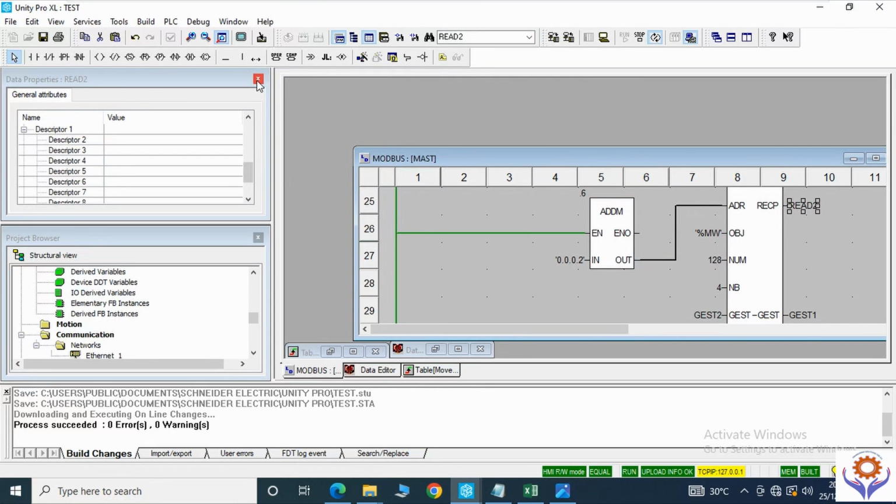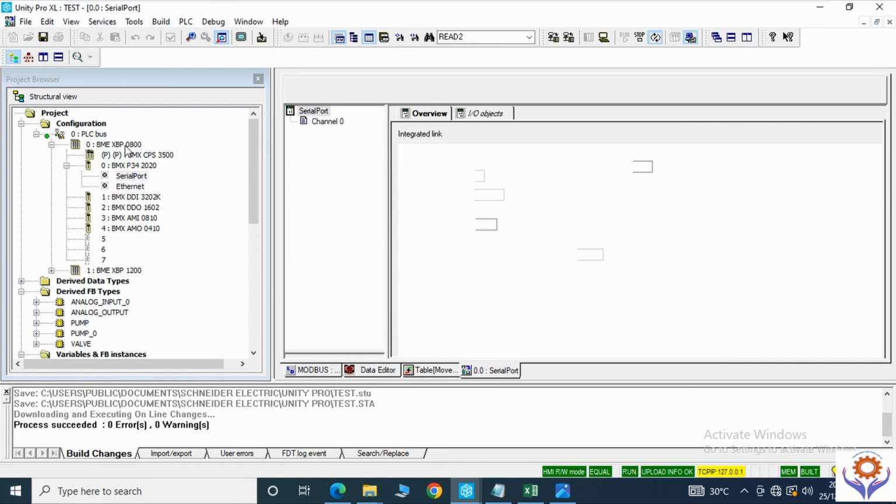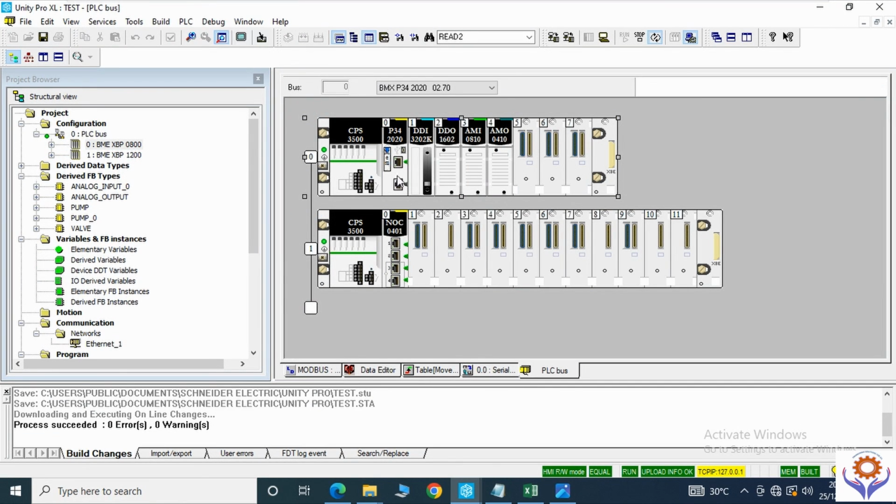For example, you need to observe the real physical device, go there, and you can observe this one blinking continuously. Okay, this one you have displayed on your M340 CPU, and if it is continuously flashing, this means there is communication. The flash should be so fast, like milliseconds, that you cannot count it.